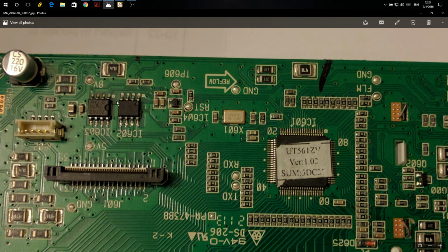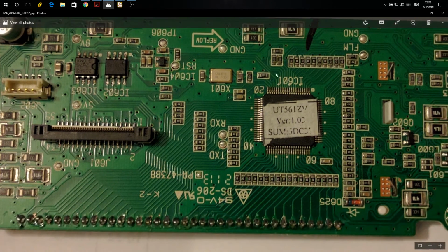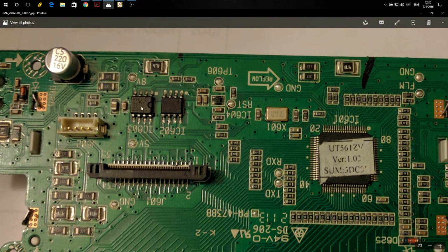If your data bus is being dragged down, it can't communicate with anything on the bus. It just will sit there in a freaked out state. And this is actually true of this radio. If I attach things to the SPI bus, it will actually freak out. There is a countermeasure in this. Okay, I want to be clear about that. There are countermeasures in this.